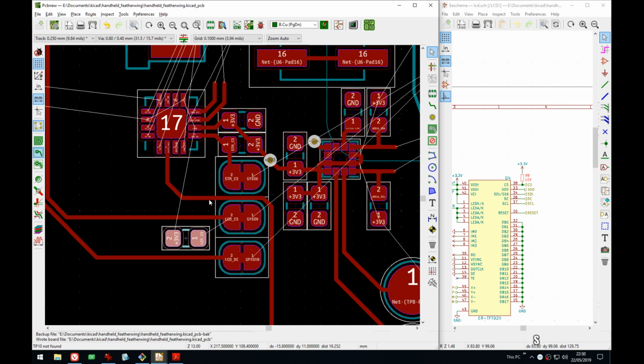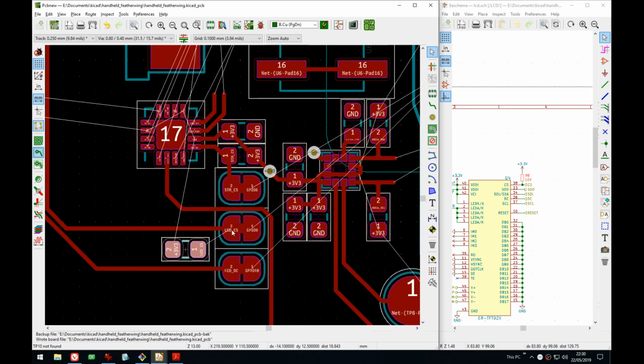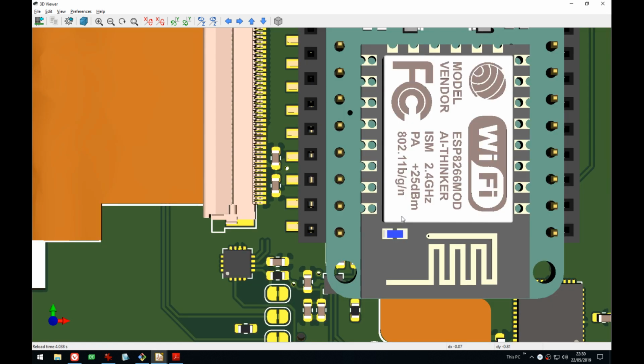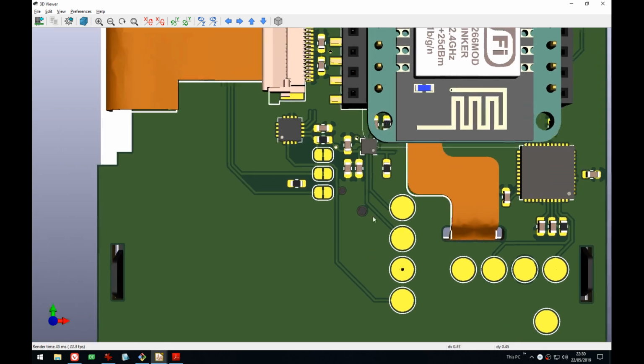Also, I'm thinking from a UX point of view, I will have the silk screen here to explain what these are, one here and here. So having the cap in the middle of that is not great. See, these are the things you have to consider. These silly things.